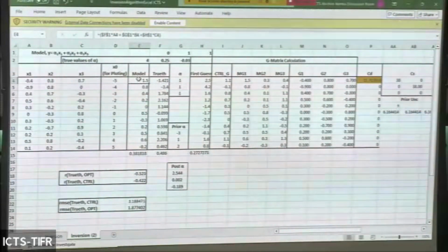Isn't it what we did earlier? Here I change alpha instead of the x parameter or x field. I change alpha, I get a column of first sensitivity, then I replace the value back to 1 here. I put it back to 1 and put 0 here, so that means I am looking at the sensitivity of alpha 2. I got the model, I copy and paste it here. Then I change alpha 3, get the model output, and copy and paste it here. So this is my G matrix. This G will be partial C by partial X, which this matrix automatically generates.